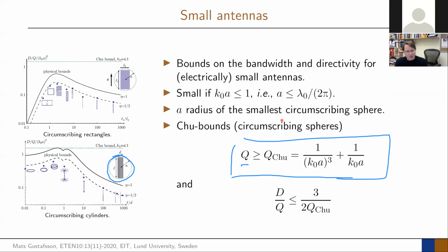And if you sit in a cellular system, you cannot live with Qs that are, for example, 100. That would mean a few percent in bandwidth. You need a lot of bandwidth. So you need to have basically low Q systems in some ways. They don't need to be ultra wideband, but they should be wideband. So it's really an issue here when you start shrinking things.